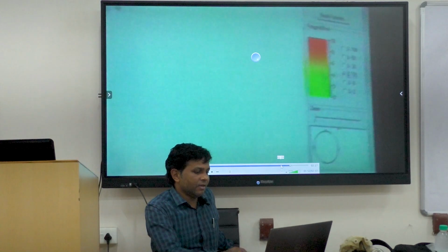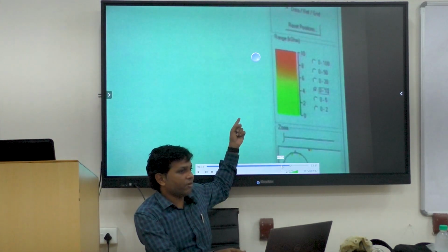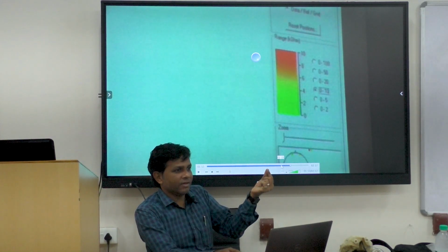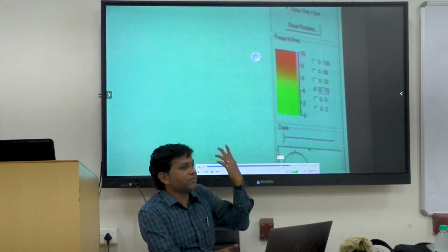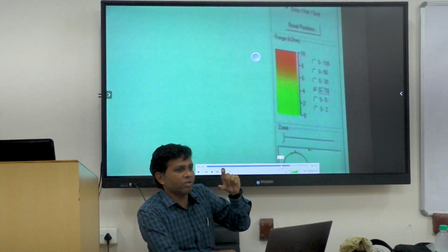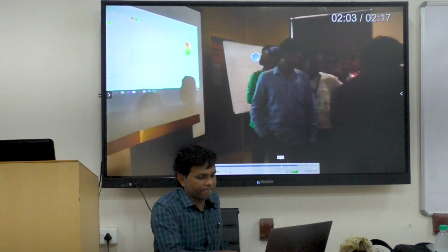If you see there, I am setting the channel ranges. As I mentioned, we have shown that alpha, beta, gamma, delta, everything has ranges, like 0 to 5, 5 to 8, 8 to 13, right? Like that, we are now going to set the ranges so that we can filter which channels we are going to record. With the predefined ranges, only those signals which you need will be captured.